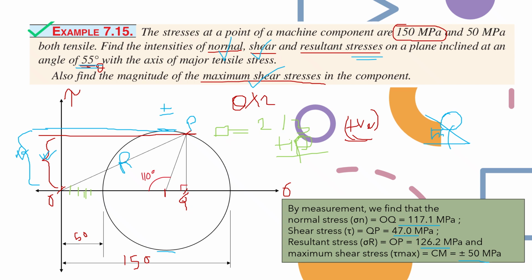In the x-axis, one small box equals 2 units, which means in the y-axis, you will also have to take one box equals 2 units. Otherwise, your calculation will vary and you will not be able to determine the Mohr circle very correctly. So you have to keep these things in mind.